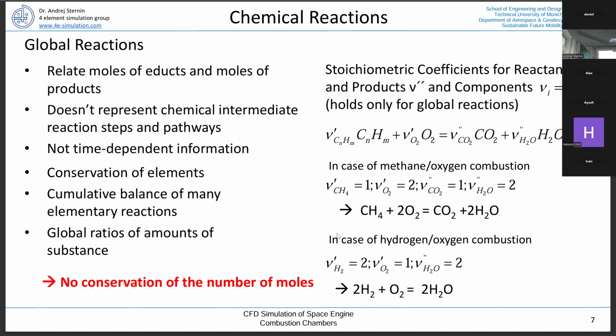Here we are only interested in how much power we need to generate. And for this, we don't typically need the elementary reactions. It would be sufficient to just take the global reaction because here we know this is the amount of fuel, this is the amount of oxygen we need in order to generate the driving gas, which is compatible with the condition in terms of temperature and mixture of the turbo pump, and that's it. So that was one way to put it into a global reaction.